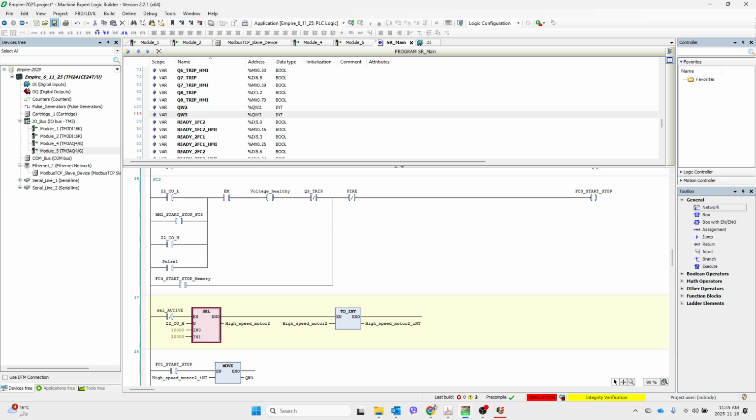One of these conditions needs to be achieved to be able to run the motor, because the frequency controller is a VLT F101. For that specific frequency controller, you need to have an analog input as a reference. In addition, you need a start command on points 12 and 20.